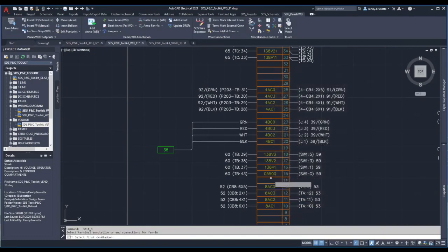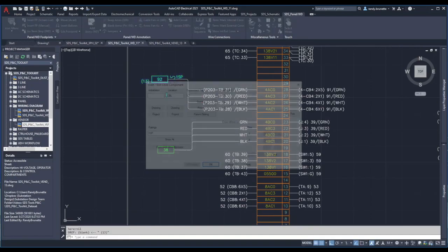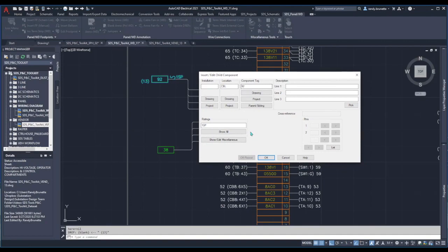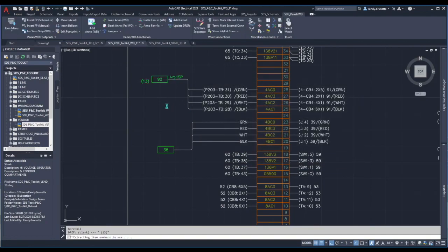Now this wire, or actually both wires, have part numbers assigned to them, but this one had a part number that had 5 wires in the cable instead of just 4 like on cable number 38. So in this case, the tool has automatically shown you that there's 1 spare wire, and it's updated the DREF option to drawing number 13, where that other end of the cable is located on the drawing. Cable 38 didn't annotate that because it doesn't exist in my data set yet.